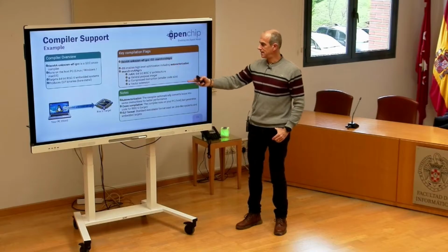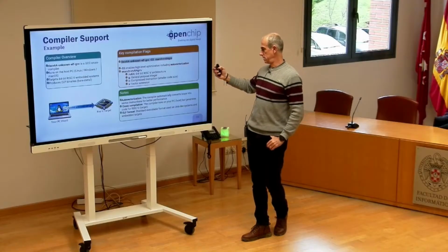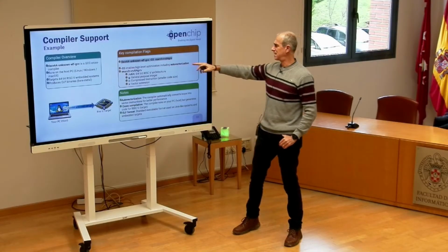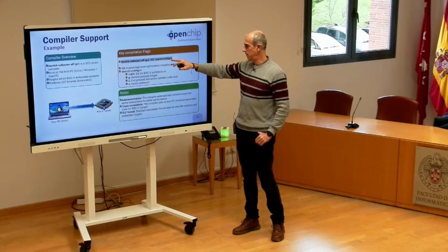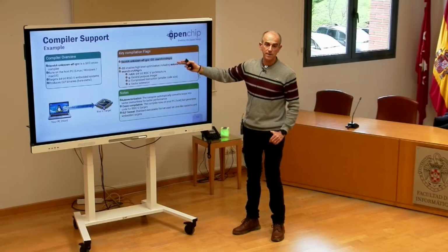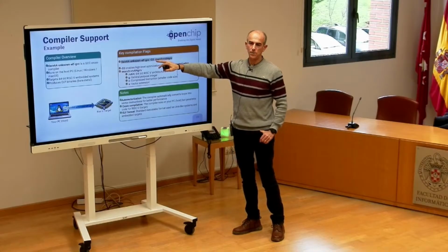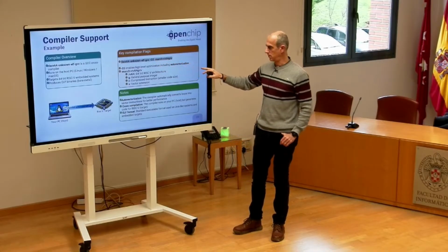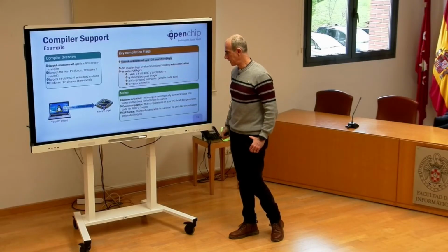G in this case stands for general. I guess this is the I extension, so the standard instruction set. Then you enable the compressed instruction set, and V stands for vector. So if you put V here, then the -O3 optimization will generate vectorized code. Otherwise, it will not.